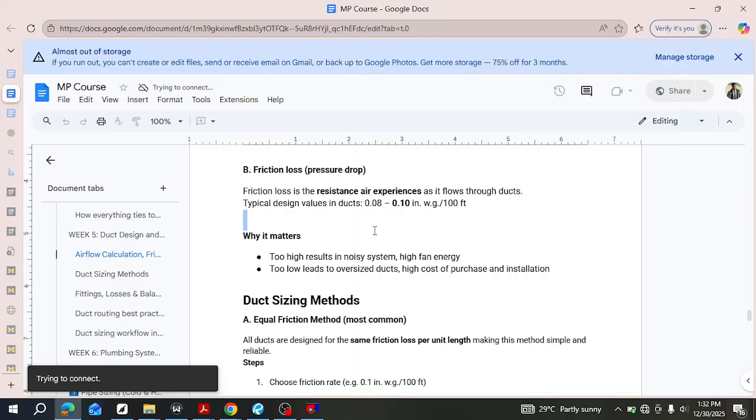But the thing now is that one of the problems with circular ducts is that attaching fittings to the sides is usually a bit tricky, because you are trying to lower any possibility of leakage. You have to make holes and attach, and for a circle, think of it like a pipe or a barrel, first of all you have to cut that flat space, and when you want to attach something on it, there's a curve.